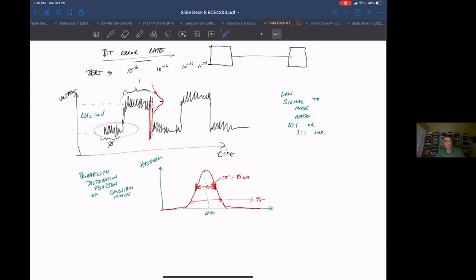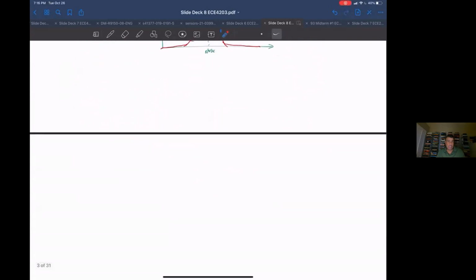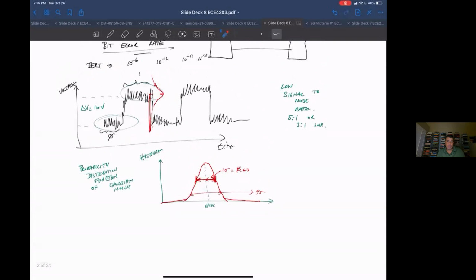But the fundamental reason, there are more reasons, but the fundamental reason I look at is that you would have a similar issue in your digital communication on chip or in your calculations, which is the same thing. Let's say you're adding two 64-bit numbers together, you could end up with an error in that calculation because of this signal to noise ratio. An error could come from this broadband noise, this errant signal coming in, and it would mess up your calculations.